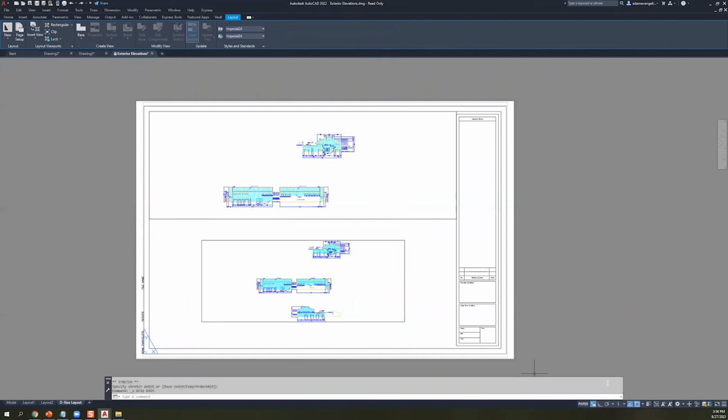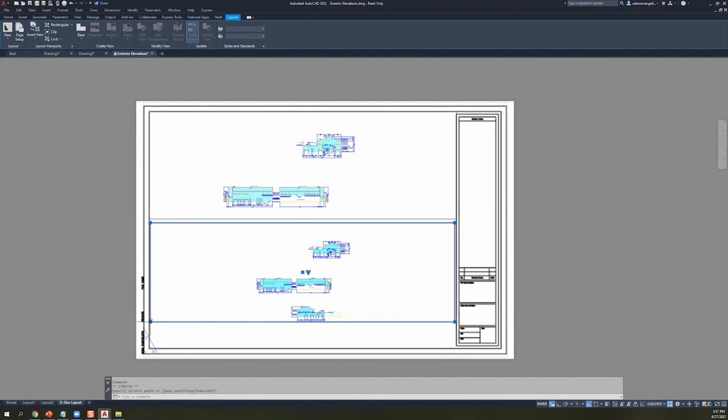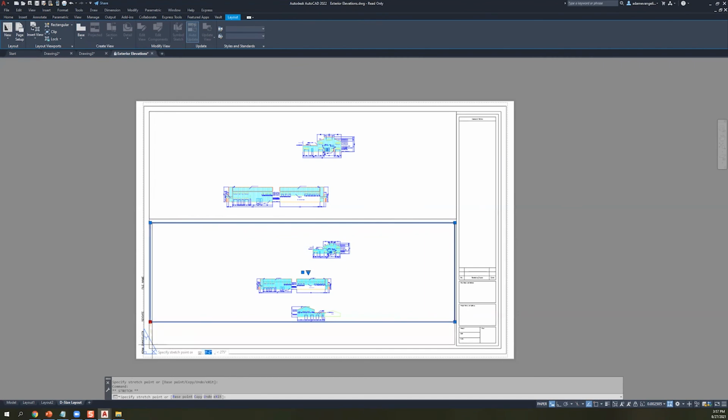And see, at this point, I'm trying to place my stuff intelligently, but my snaps are getting in the way. So I might just turn off object snaps and place this a bit more intentionally, right? Something like that. Because again, I'm not worried about the snaps or the closures at this point. I just need it to have enough space to breathe and set up my views as I want them to, right? So in this case, it's just going to be top and bottom, right?